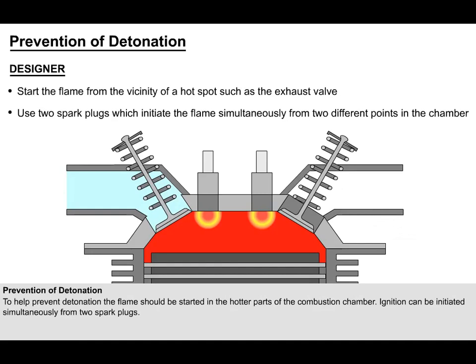In order to reduce the time taken for the flame front to travel across the combustion chamber and therefore the risk of detonation, some engines are designed with two spark plugs which initiate the flame simultaneously from two different points in the chamber.